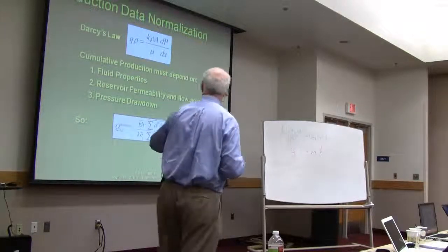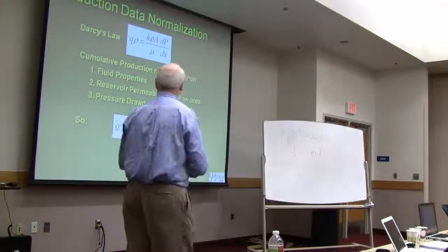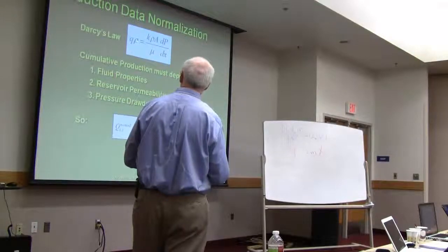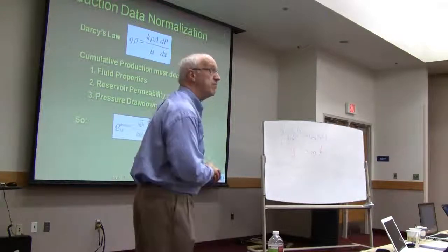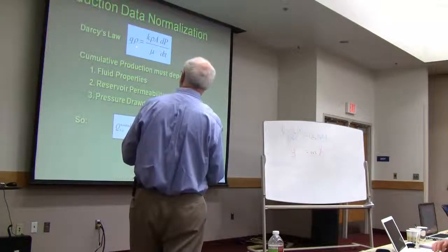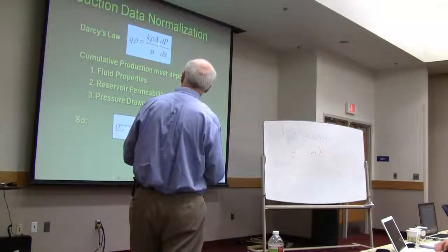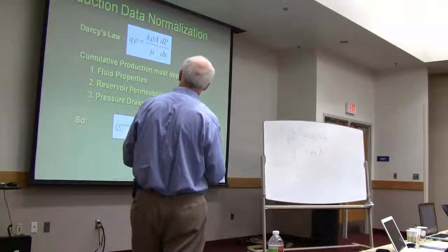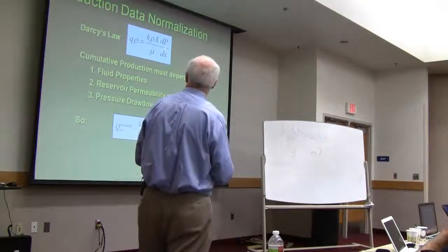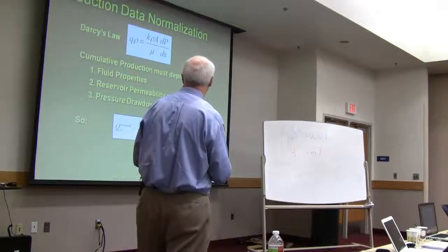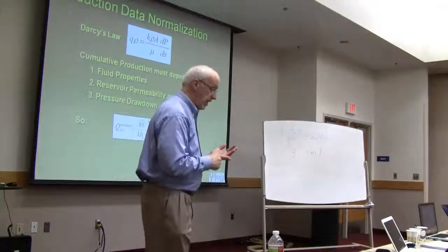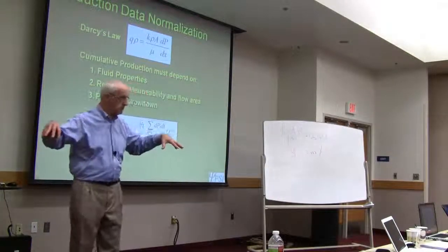And so that introduces this idea of normalization. Darcy's law says, and this is good old Darcy himself, 1856, Q rho, the pounds of stuff produced, oh, those darn chem engineers, is proportional to a transmissibility term that talks about the area, like in the frac job, the transmissibility, and the drawdown.